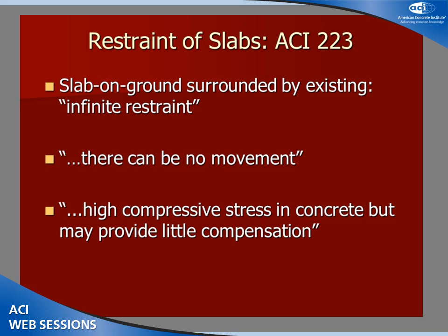Basically, slab on ground surrounded by existing will have infinite restraint. The specification says there can be no movement, and the situation will result in high compressive stress, but may provide little compensation. So in other words, you will induce a stress because of the material expansion, but will not achieve displacement.